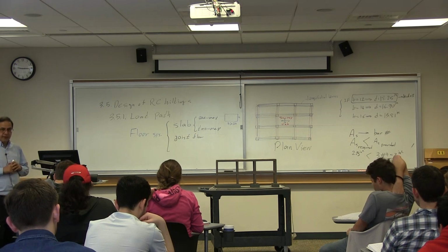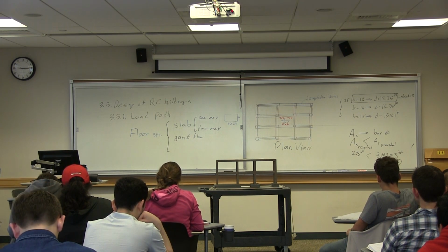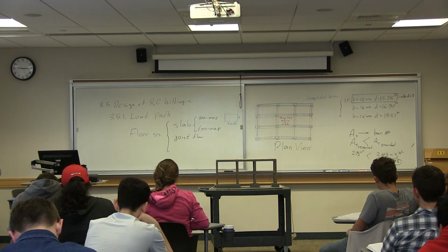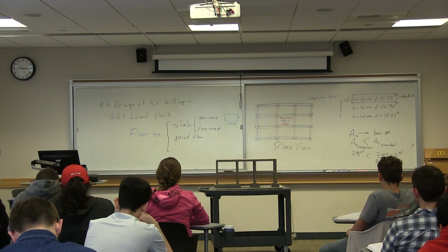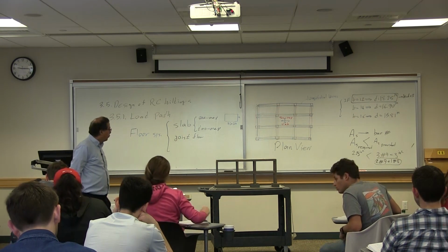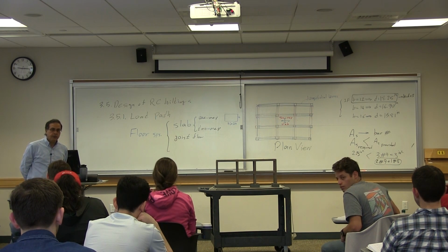Any other enhanced version of that answer? Load follows stiffness. Shorter direction. That's correct. Shorter direction is stiffer. Why would the direction that is stiffer take more load?